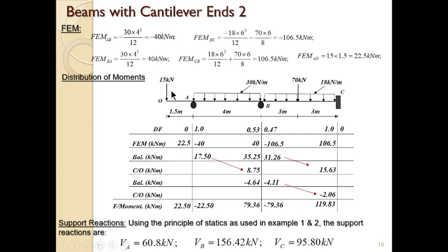At this point, remember, the moment here is 22.5. Why is it 22.5 when what we did here is anti-clockwise? The explanation is that this moment here is anti-clockwise, but the moment we always keep as fixed moment is the resistive moment. So if this is anti-clockwise, the resistive moment has to be clockwise. That's why we have this 22.5. But then the anti-clockwise is actually at this point.